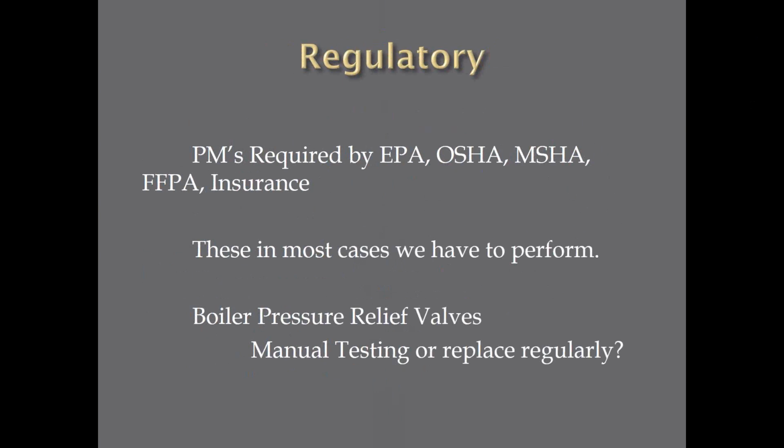My comment was always, I'm not going to do that because every time I pull the lever to test the relief valve, it leaks by. And it leaks until I can get down on the next annual shutdown to change the valve out. So I said, I'm not testing them manually. And he says, well, it's required by law that you do that. I said, what's my other option? Well, if you don't do that, you have to change them out every year or every 2 years and rebuild them. So I took that option.